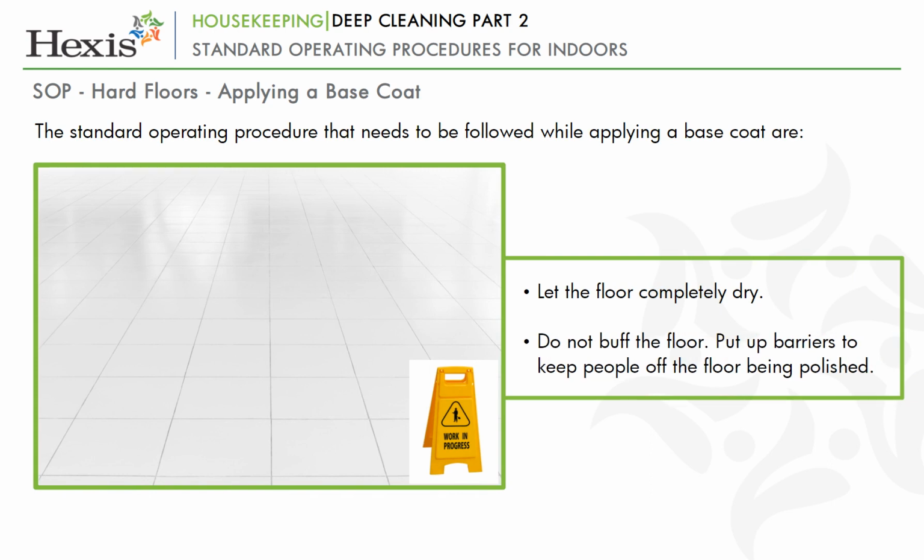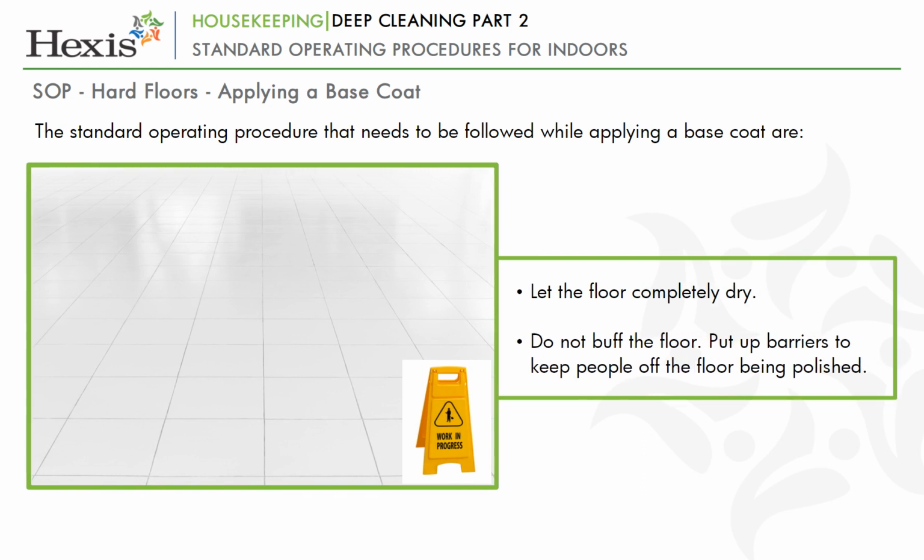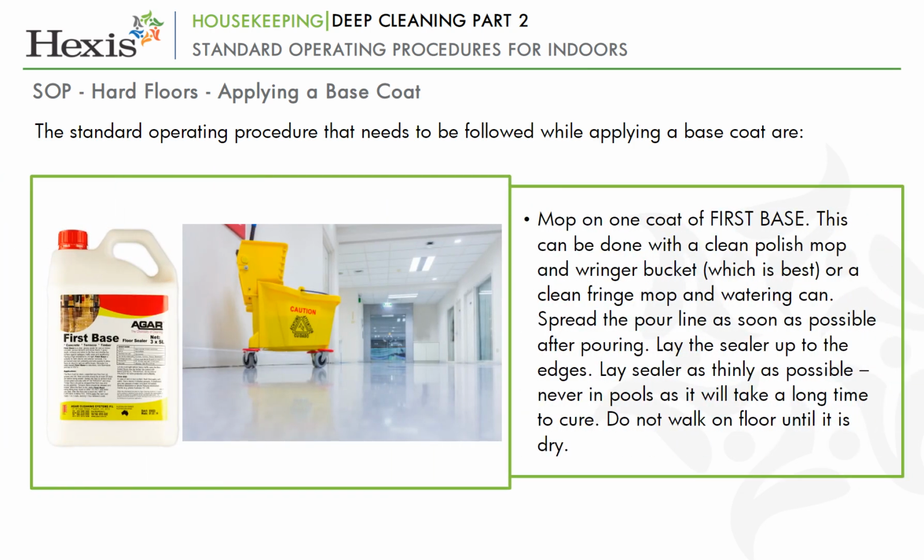Put up barriers to keep people off the floor being polished. Mop on one coat of first base. This can be done with a clean polish mop and wring a bucket after pouring. Lay the sealer up to the edges. Lay sealer as thinly as possible. Never in pools as it will take a long time to cure.